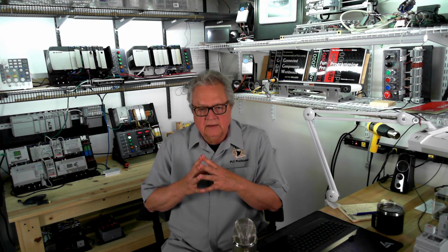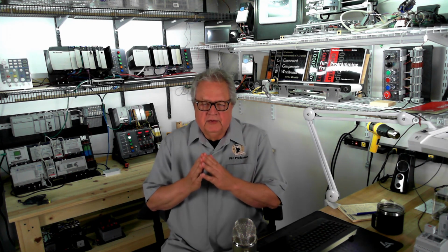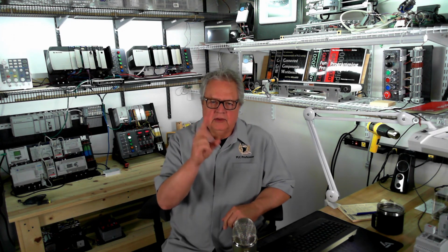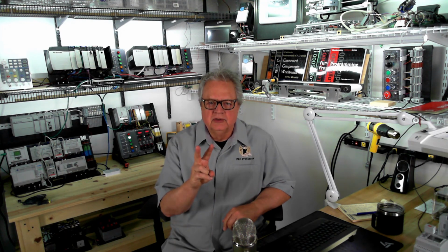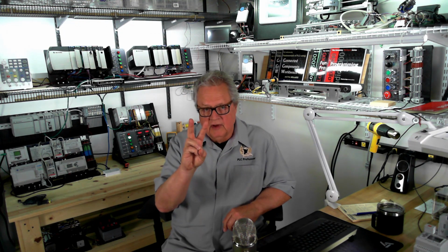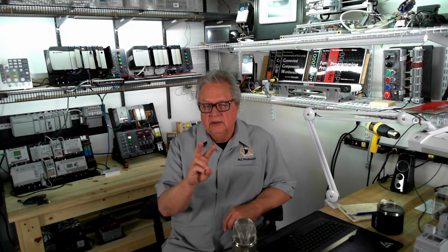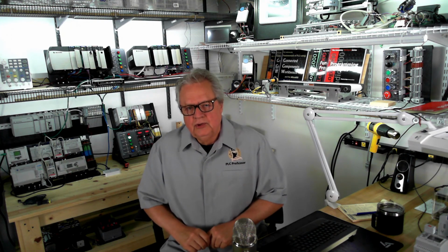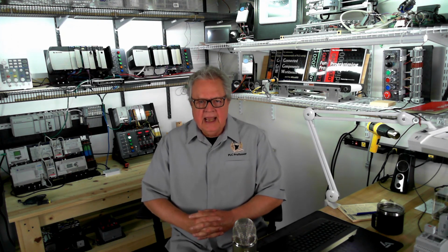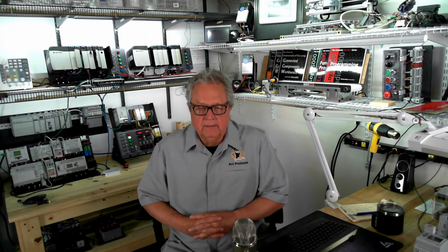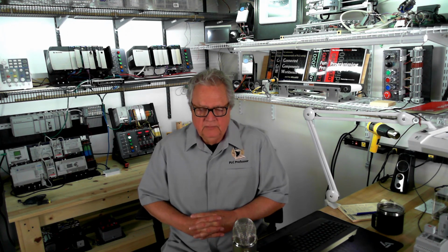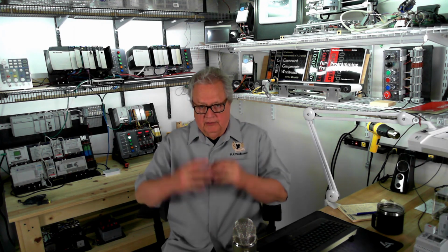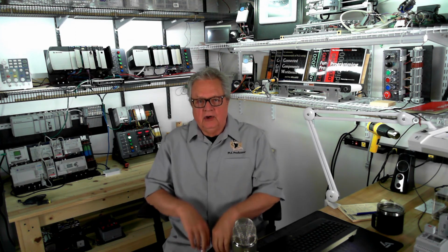Last man standing. Remember that the previous lab was one rung of logic with two instructions, two memory locations. We exhausted that relationship. This lab project is two rungs of logic using the same memory locations, more or less, and then flipping the rungs around to produce something we call scan-dependent logic, meaning that if you put the rungs in a different order, in other words, you take the two rungs and flip them, you're going to get a different result.